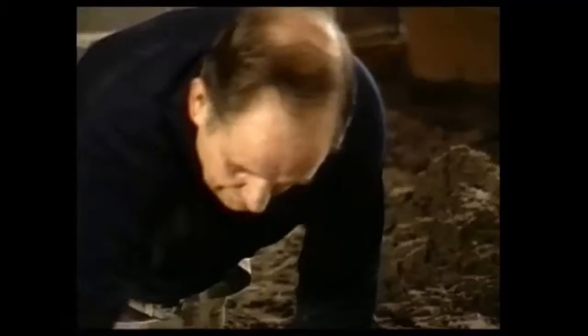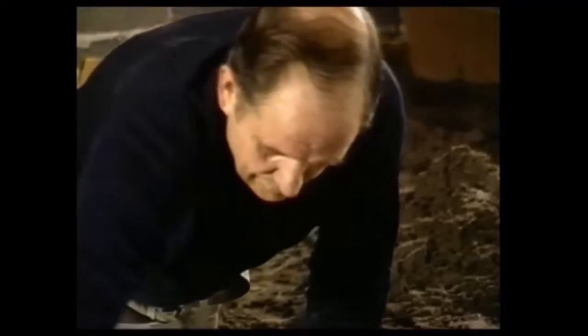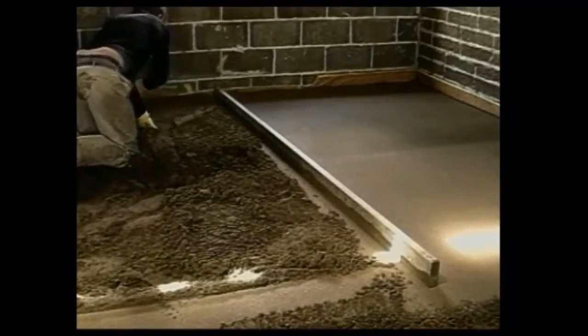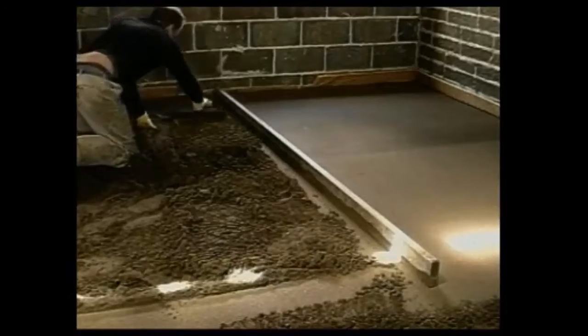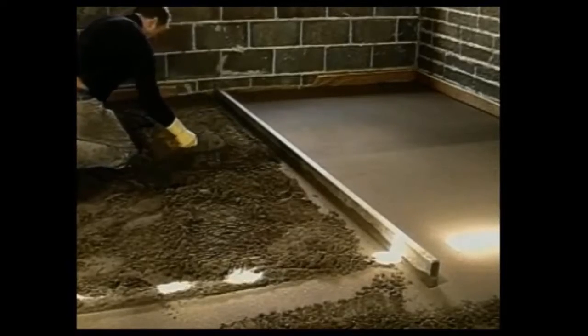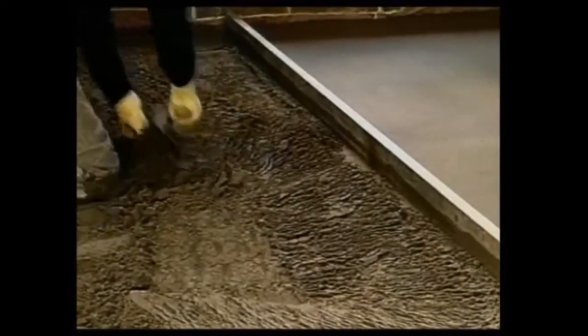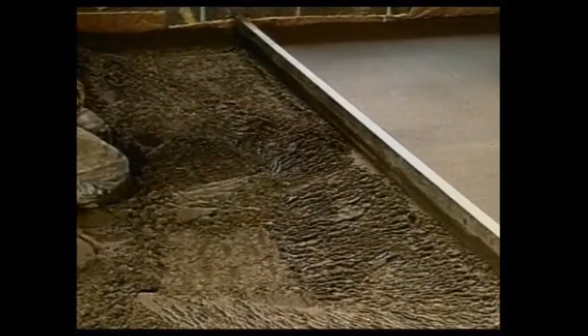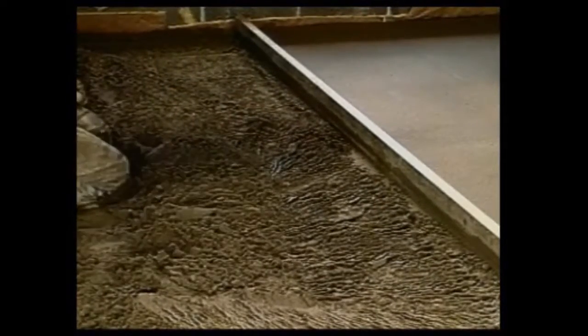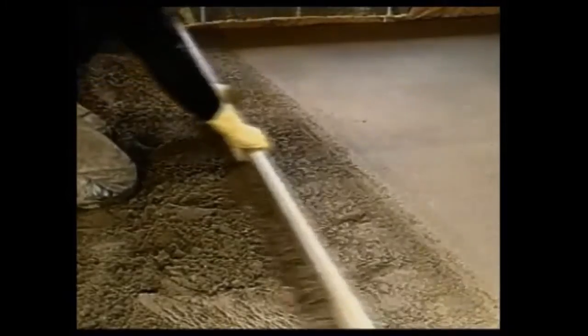On a clean concrete slab, the thickness should be about 40 to 50 millimetres. If the screed is less than 40 millimetres, it may dry too quickly and cracking will occur. To obtain a smooth, even surface, the screed is levelled with a straight edge and finished with a steel float. Some screeds are also compacted mechanically.